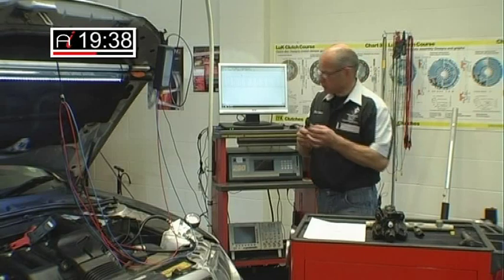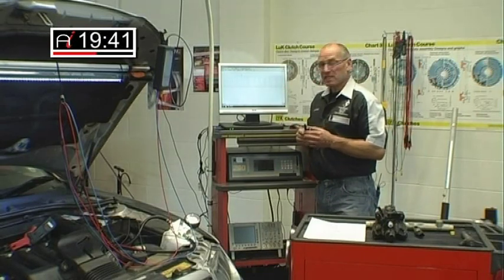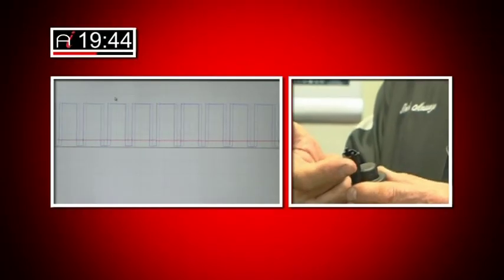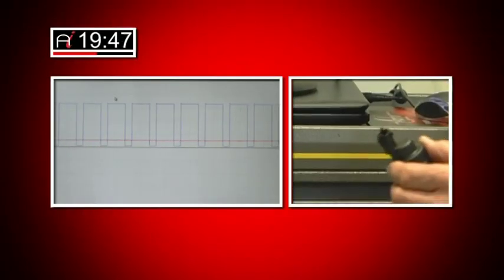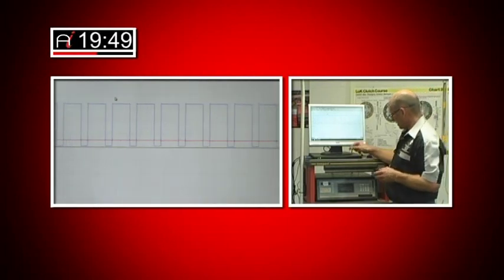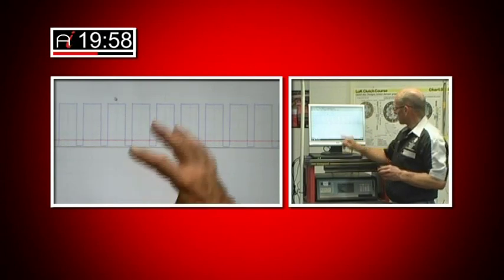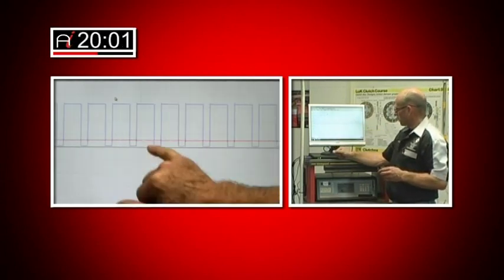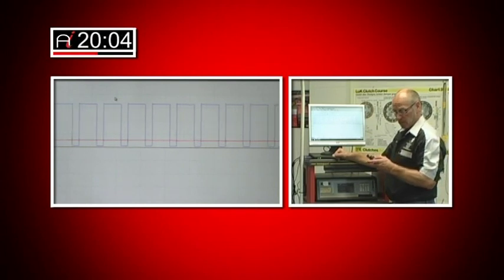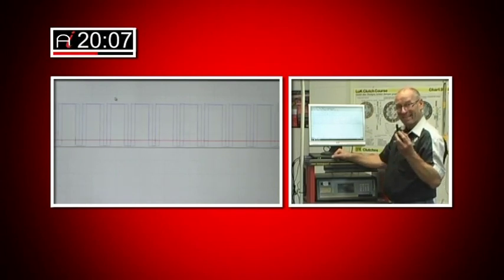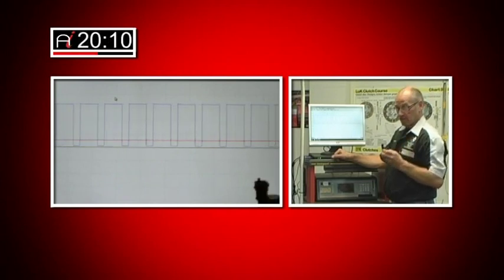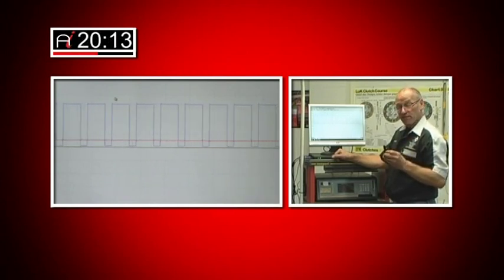So what we're looking at there is the control event to the DRV. It is permanently fed with power and is ground switched through the computer. So ground is the on event, and you can see from that that it is more off than on, and roughly 75 off, 25 on. The correct duty for this vehicle running at idle is around 18% on from this valve with 1.3 volts from the rail pressure sensor, which equates to 300 bar. That's the balance I want to see.